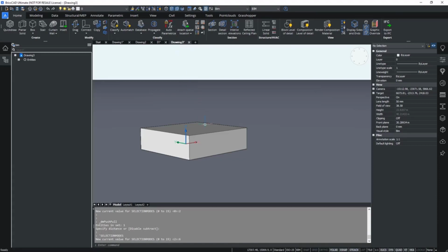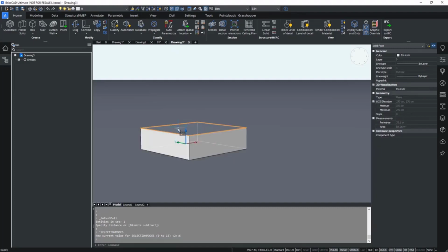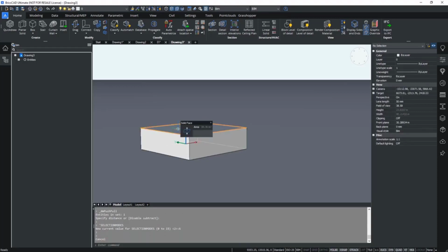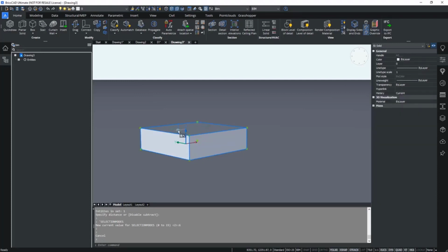This means if I hover over an entity, I immediately highlight the solid face. Once I click, I can also select the solid face. Now, how do I select a solid entirely when the face detection is prioritized? You simply hold down Ctrl, and then you can highlight the entire solid. As soon as I now click, you will select the entire entity.